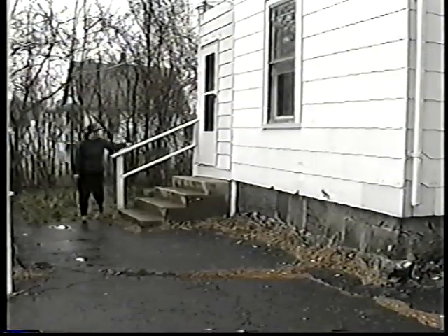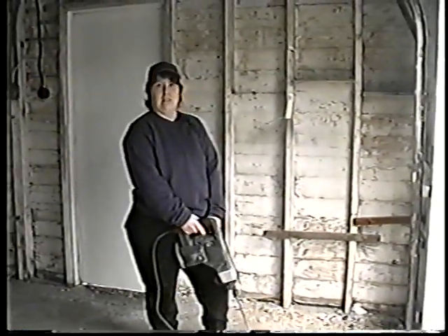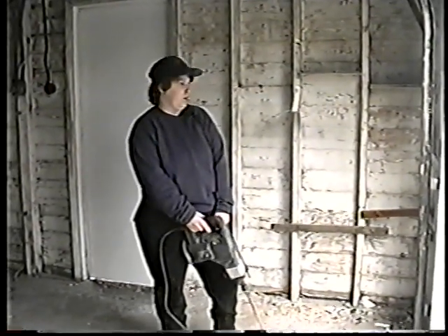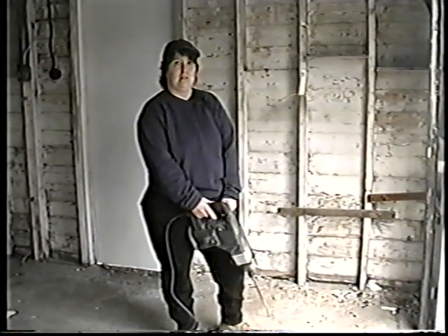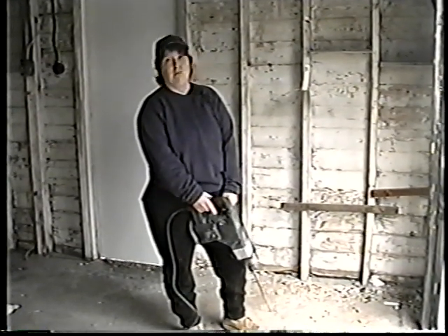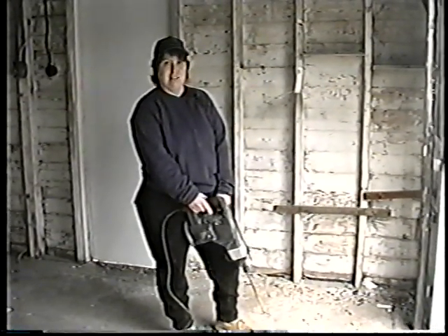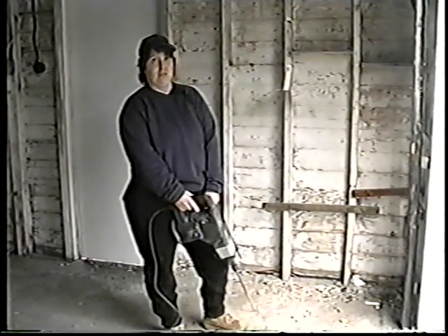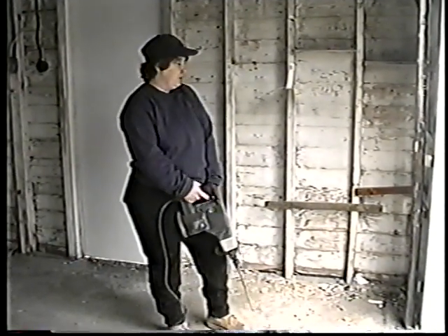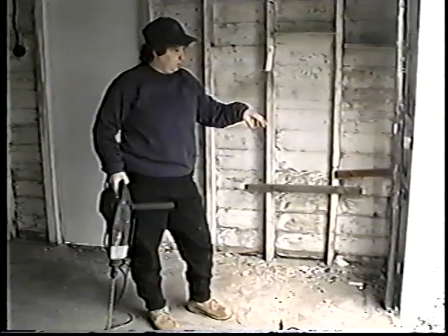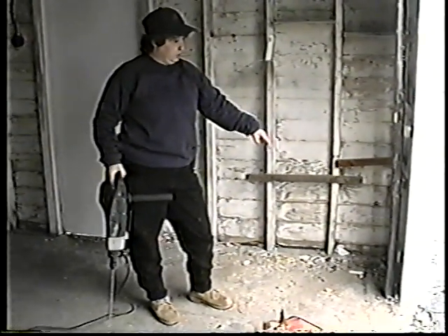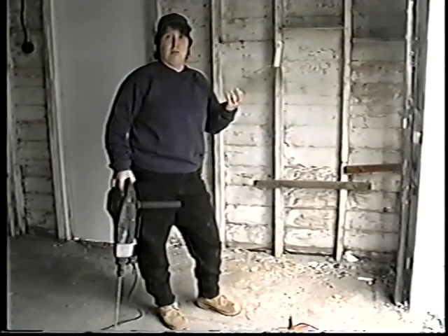What we're going to do now is we're going to do the drilling in the garage, because we did find termites. What we have to do to protect the garage from the termites is we have to make a full barrier with a liquid termiticide around both the inside and the outside. We achieve this by drilling holes around the foundation, and we're going to inject a chemical application of liquid in, which is basically going to come up around the footing there so that the termites can't get up to the wood.